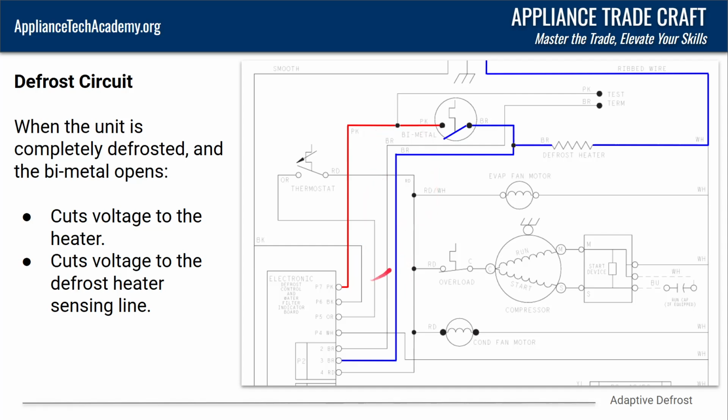And this is one of the things I keep talking about. A, isolating your problem, so that we're not focused on all the other wires, and B, making your checks from the board. I still talk to techs all the time who have the whole unit defrosted. They spent 15, 20 minutes steaming it out. Defrost heater checked good. This checked good. Make your checks from the board. It's not that difficult. I mean, see right there? And it's really simplified when you've got the lines going through it, but there, you got that there.